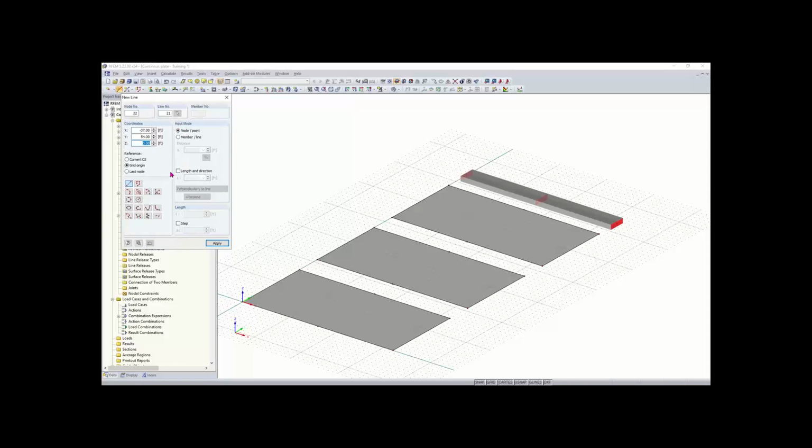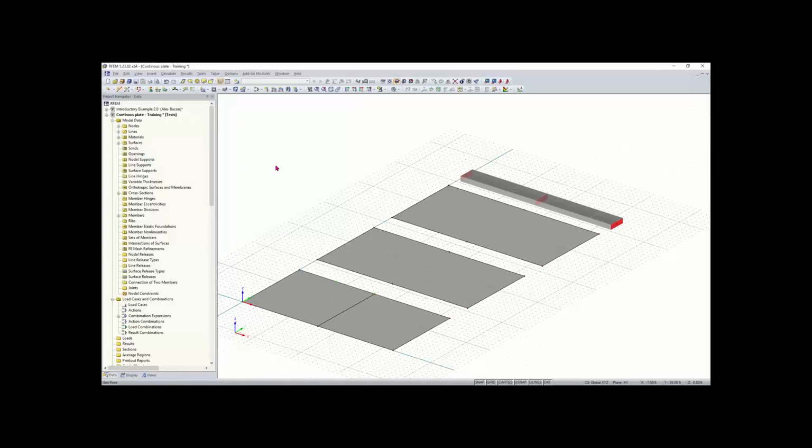Now you can see this box opens up here, and what we can do is just draw our line within our work plane here. I'm just going to select snap to and select this first node here, and then I'm going to draw it and snap to the second node. And you can see we have a nice perpendicular symbol there letting me know that the line is perpendicular. And I can right click anywhere or hit escape to exit out of that tool. And now you can see that our line was drawn.